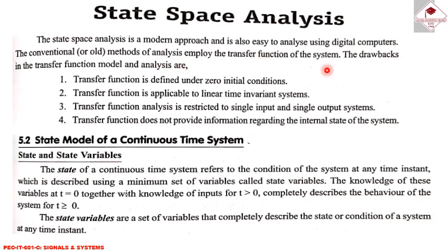The drawbacks of the transfer function are: it is defined under zero initial conditions, it is applicable only to linear time invariant systems, it is restricted to single input and single output systems, and it does not provide information regarding the internal state of the system.